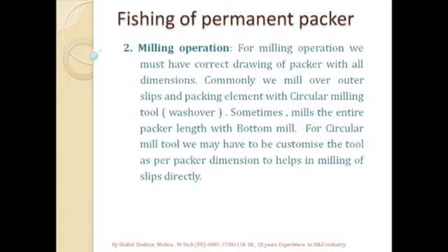If we don't have the correct OD of the packer and the distance of the sleeve from the packer top, we cannot judge while milling whether we are milling on the body itself or on the sleeves.